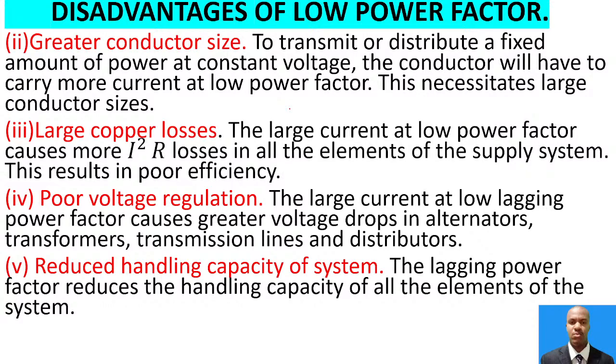So the lag in power factor reduces the handling capacity of all the elements in the system, and that is because the reactive component of the current prevents the full utilization of the installed capacities of the elements.